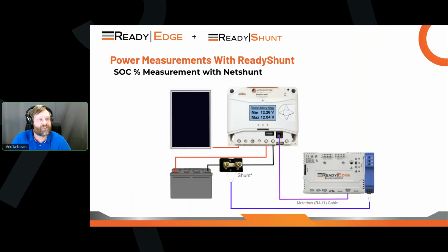A lot of customers prefer percentage-based SOC as opposed to voltage. And when it comes to newer chemistries like lithium or supercapacitors, sodium ion, the shunt as configured as a net shunt gives you much better visibility into the state of charge of your battery using our SOC algorithm.